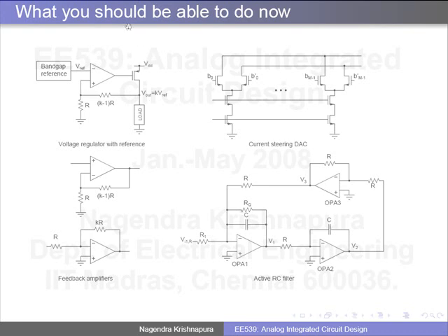Usually the speed requirements are low in absolute terms. You're not looking for tens of megahertz of bandwidth usually, but because this transistor is large, it introduces a parasitic capacitance here, which is also large. So you will still end up with a reasonable problem for stability and frequency compensation. This is what you see inside most voltage regulators.